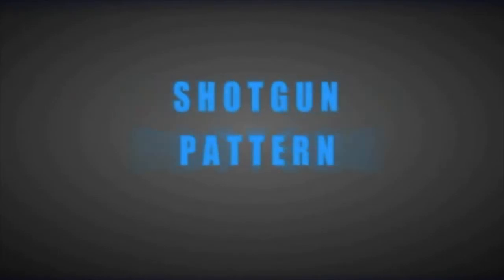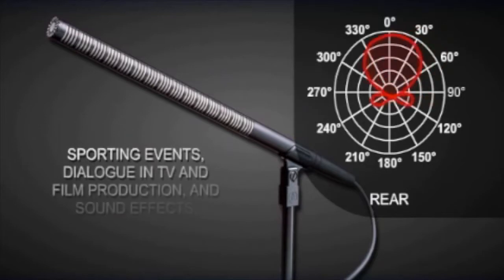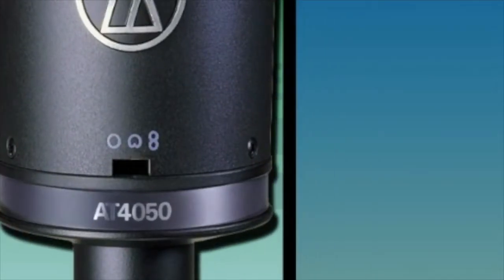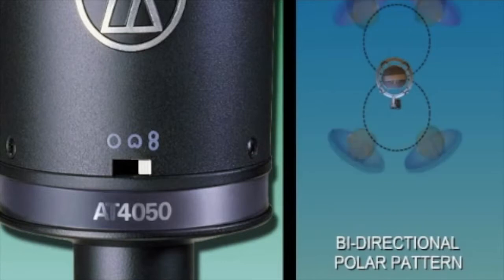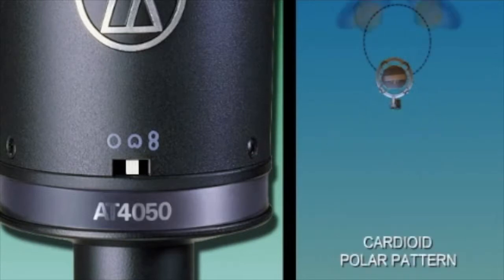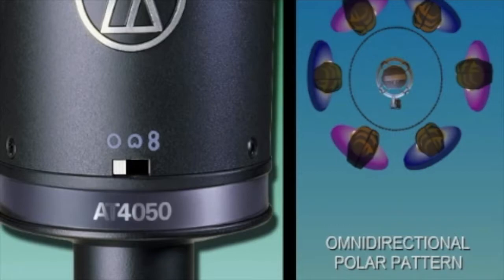A shotgun pattern is a highly directional pattern used for sporting events, dialogue in TV and film production, and sound effects. Some condenser microphones feature a switch that allows the user to select one of multiple pickup patterns. This is achieved by manipulating the properties of the diaphragm electronically. This versatility allows the microphone to be used in various applications.